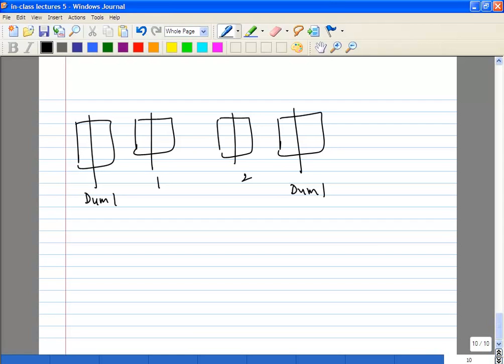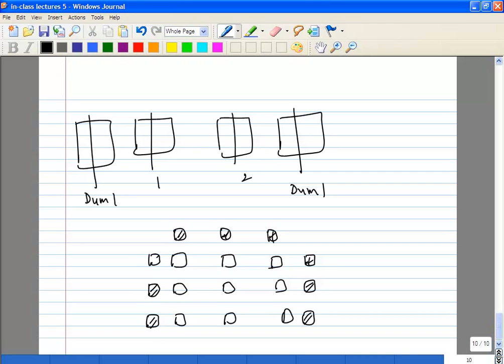And in reality, you want to have dummies in all directions. In this case I have shown a very simple array. So let's say you have something like this. Your transistor is laid out in 9 sections. You probably want to have dummies in all directions actually. You want to have something like this such that it's protected on all sides, and ideally these dummies will be identical to your main transistor section. So every transistor in all directions will see the same number of devices and the same environment.